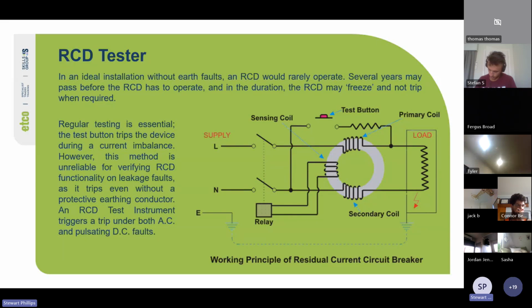Basically, every time you check your smoke alarms, you check your smoke alarm every 6 months, test your RCDs every 6 months, which is a bit laborious if you have RCBOs, which is my preferred install. I hardly ever install RCDs anymore.